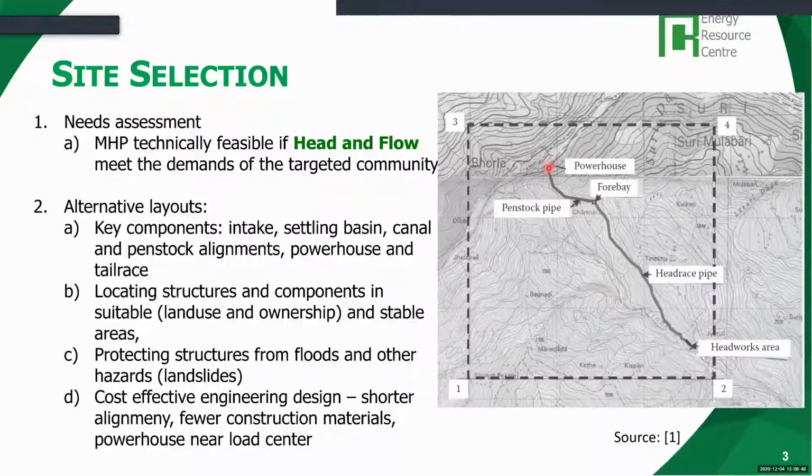Also, when you build the powerhouse, you have to make sure that it is protected from floods. If there is a flood, like in Majau, I think in 2015, you had a high rainfall and a flood, and it destroyed the powerhouse. So the powerhouse location should be above the flood level. And this flood level depends on the size of the project. It should not just be above the normal annual flood, but also above, let's say, floods that happen one in 25 years or 50 years, because this can happen during the lifetime of the project.